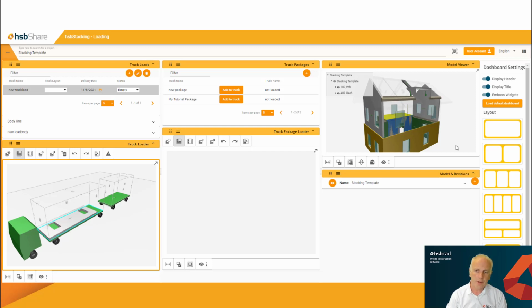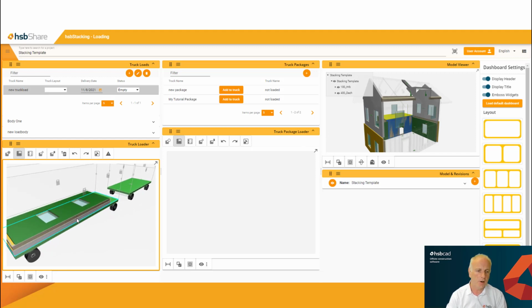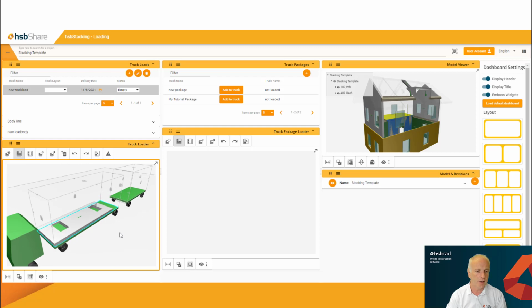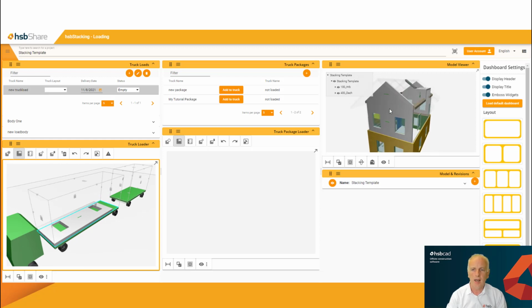Now I'm going to deliberately make a mistake here, and pick the next panel below it, which is the incorrect panel in this case. I wanted to select, for example, this panel. So that's no harm. All I need to do is select the element and say remove from the stack, and that will allow you to remove it. So we can continue to proceed, and I can now place this particular element here. And you can see it places it on a stack.